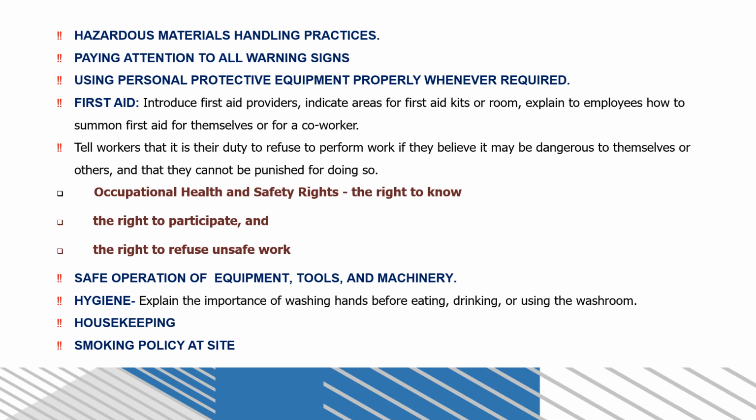And all this, the day when any hazardous activity, for example radiography, is going to be conducted, in the very beginning, in the morning shift, in the toolbox talk, all the crew members, all the workforce are introduced and informed that today we have this plant, so this area will be affected, and the area will be barricaded, there will be signage over there, so keep yourself away from that affected area.